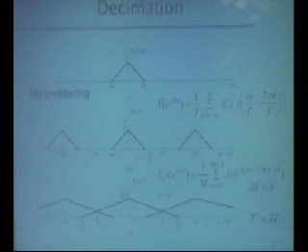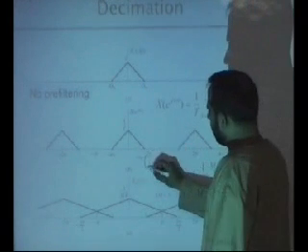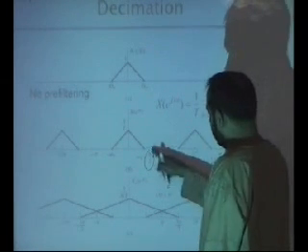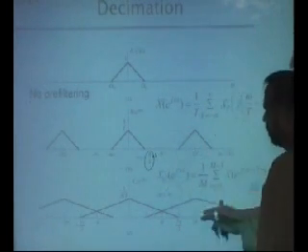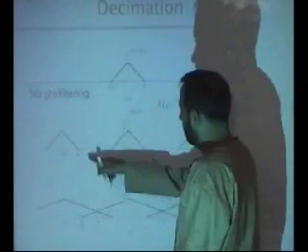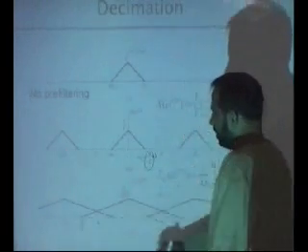If I ask you to downsample it by 3, that means keep one sample and throw away 2 samples, keep one out of every 3. So use the same trick: pi by 2 multiplied by 3 gives 3 pi by 2, and similarly this will be at minus 3 pi by 2.